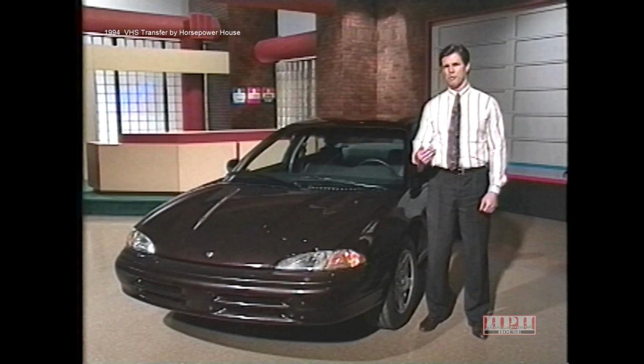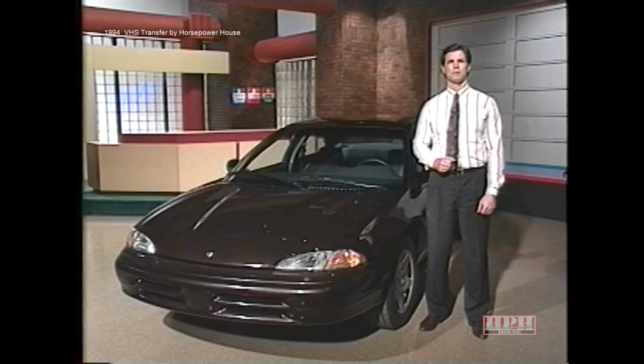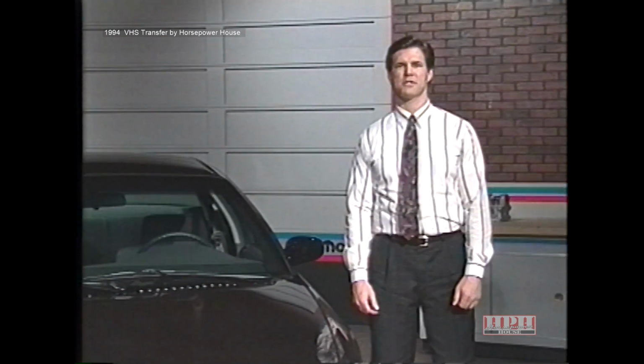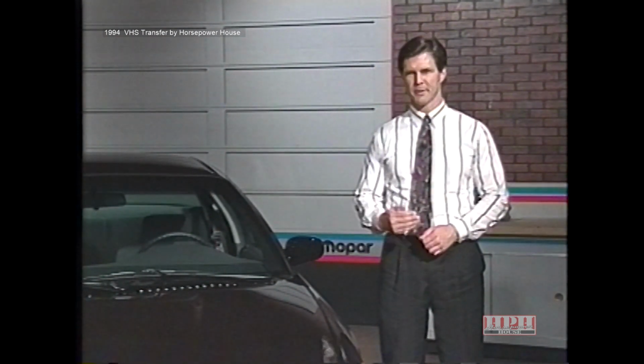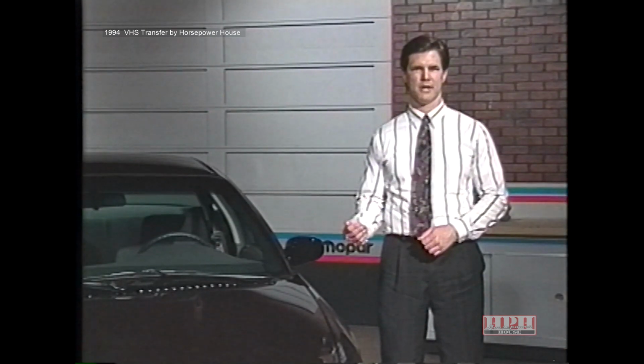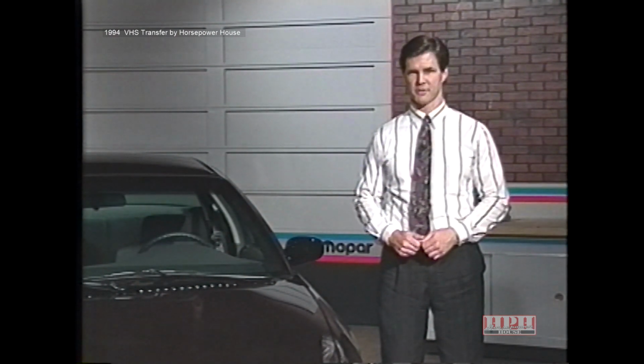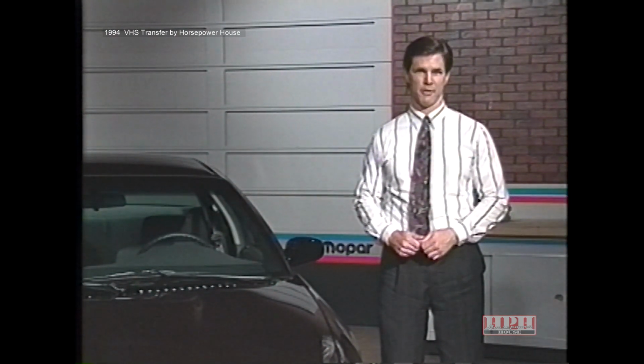Before we get into the actual repair procedures for each area, let's first briefly review the diagnostic procedures you should go through to pinpoint the area of concern. Keep in mind only wind and traffic noise diagnostic procedures will be covered here. The first step to diagnosing wind and traffic noise is to get a complete description of the type of noise and where it seems to be located from the customer. If the customer is unsure, you may want to go on a road test with the customer and have them point out what they're hearing.